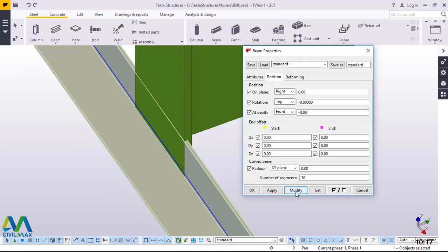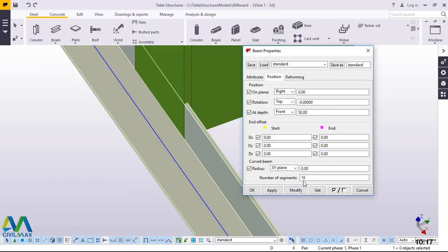and it's still clashing with that member. What we'll do is slightly move it up, slightly move it front right there, and put some dimension here to offset it upward. Just feed 50 millimeter right there and take it up.